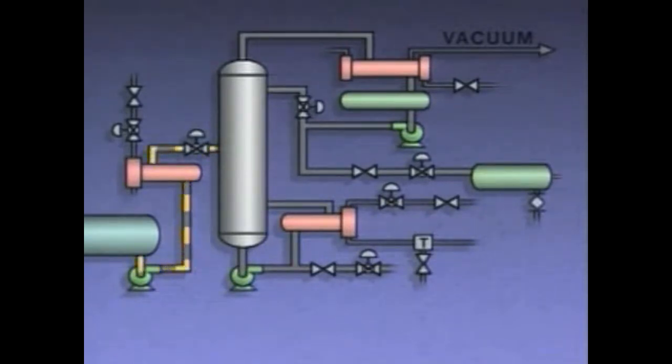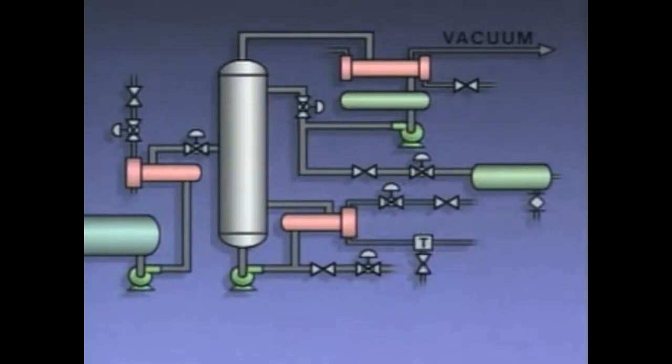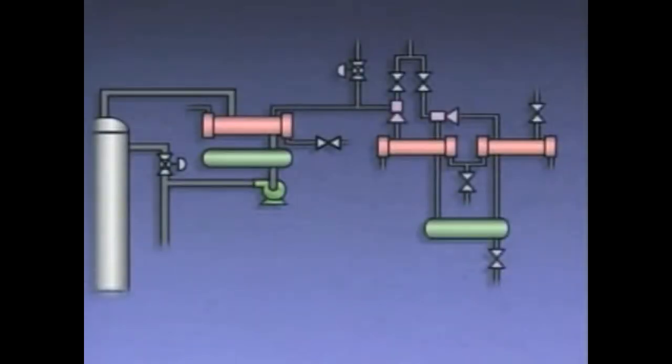When the mixture in the column reaches a specified level, the operator closes the valve by moving the flow controller set point to 0. Since no mixture is flowing from the feed tank to the column, the feed pump needs to be turned off to prevent it from overheating. Next, before the mixture in the bottom of the column is heated, the vacuum system is started up.